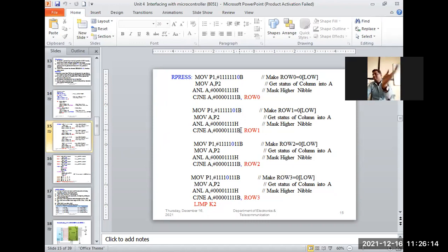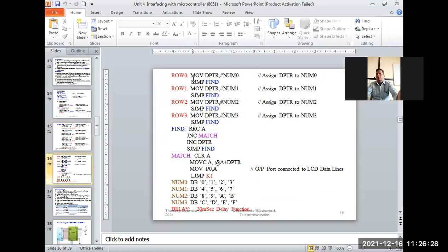And row 1 is defined. Next, at that time I'm taking the data pointer value and transferring it. If you see here, when the 0 button is pressed, I'm taking the value 0 1 2 3 into the data pointer. If you see R0, MOV DPTR, #number. So I'm sending the number from that key button, the number 0 will display. I have the data pointer values 0 1 2 3 for the first row. So for the 4 buttons, 0 1 2 3, when I press them, that will be displayed, going to port 1 from the accumulator.